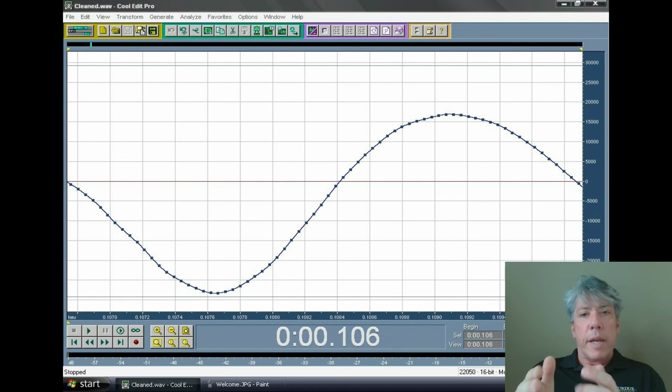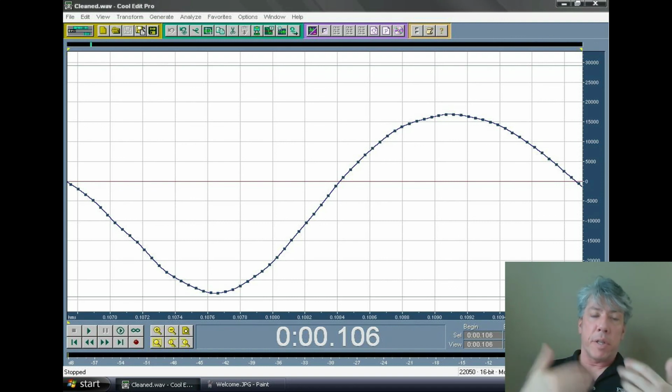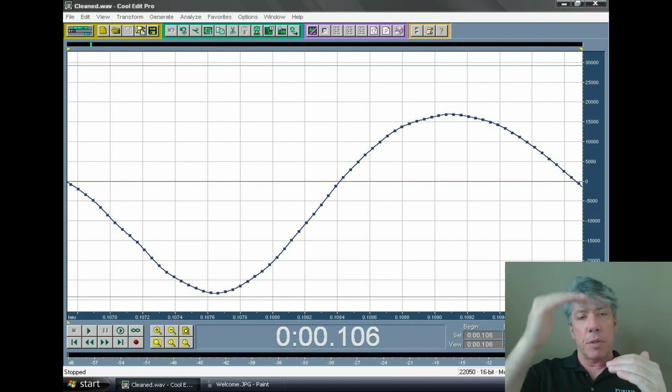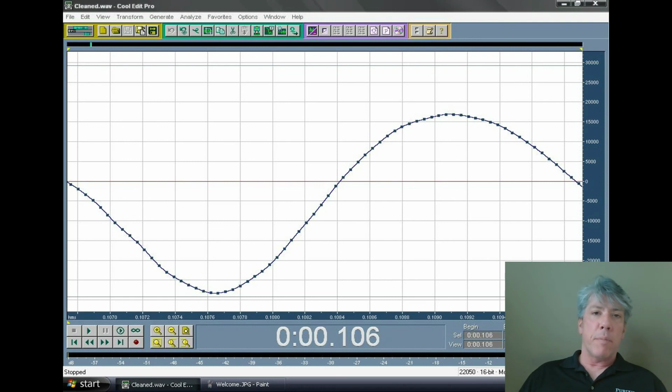So the point here is that we're giving up something, right? We're trading off the continuous signal, the actual signal from the sensor, in this case a microphone. We're trading that off for a version of that signal that has been discretized in amplitude. Pretty good resolution. I mean, what if you have a tank and you're trying to measure the level in the tank? So you've got a level sensor. If you could have 65535 or 65536 different heights in that tank, that's probably adequate, right?